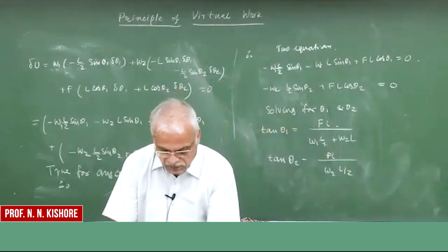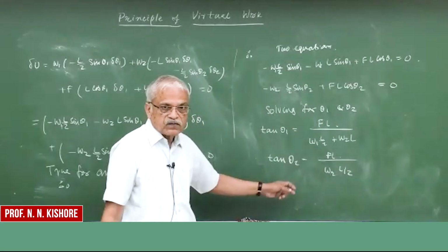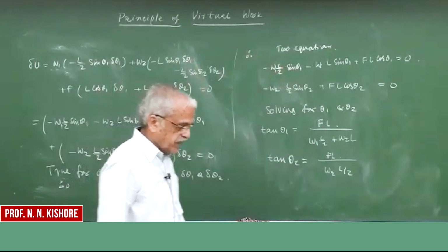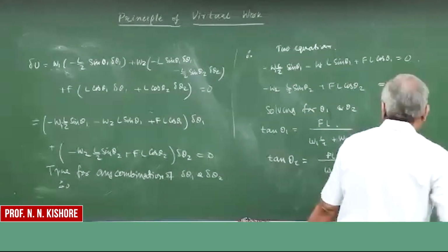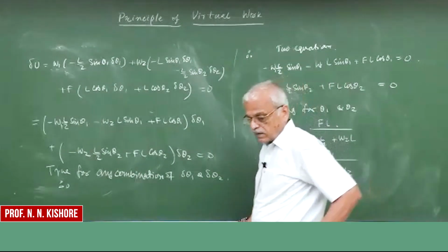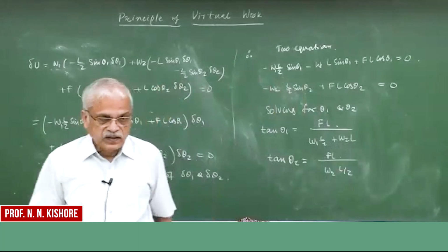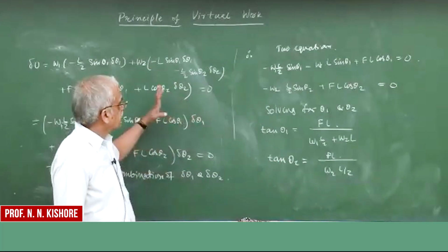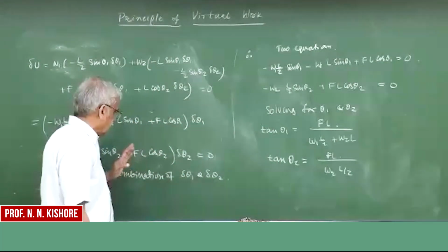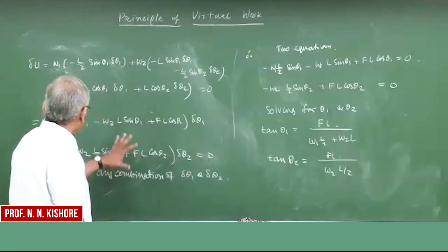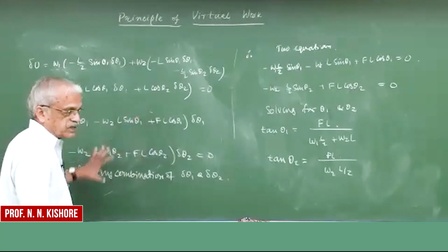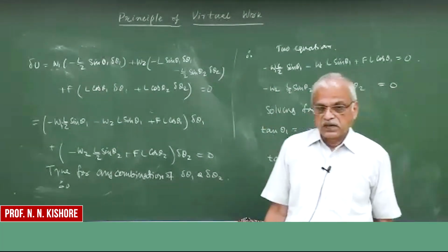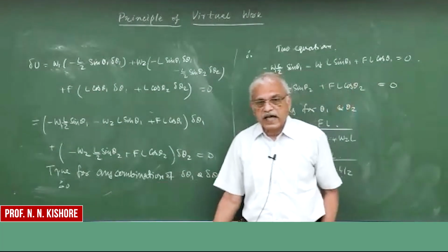Okay, so thus we are able to solve for theta 1 and theta 2 by this application of the principle of virtual work. What is the beauty of this procedure? The virtual work equation will involve only those forces which will do the work, and we call them active forces.